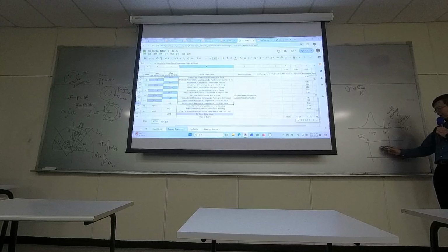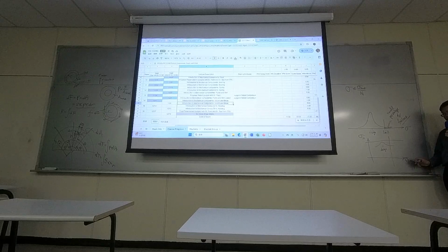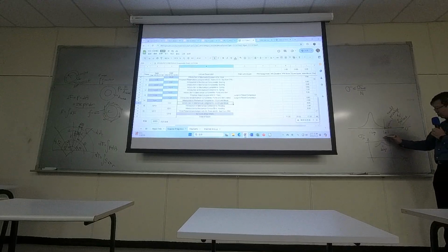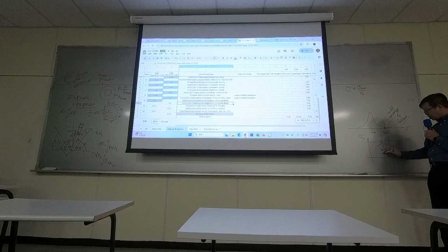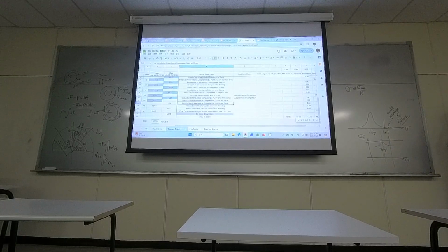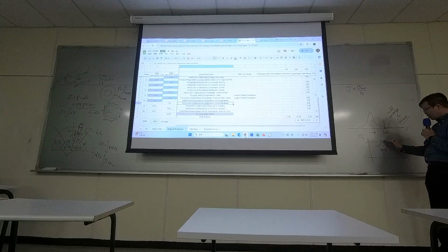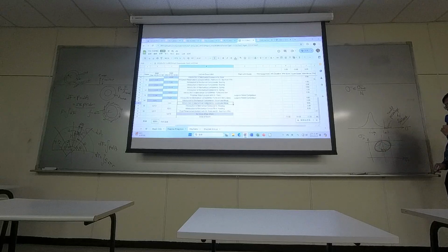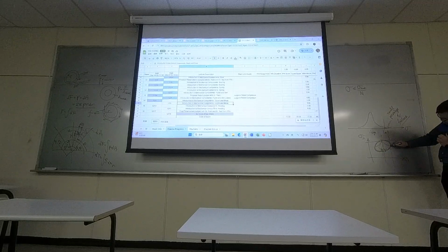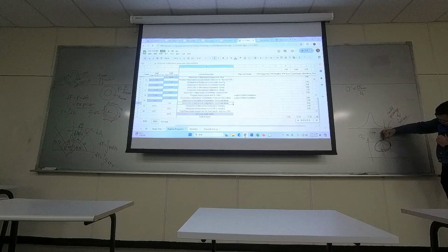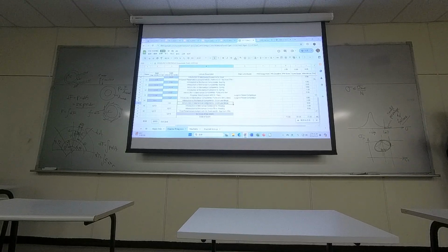So your design may have a normal distribution along the first stress direction, and also a normal distribution along the second stress direction. So in fact, overall, the random distribution looks like an ellipse. So your failure probability is right here and here. So it becomes a multi-dimensional problem. I would like to share with you how you deal with a multi-dimensional reliability problem.